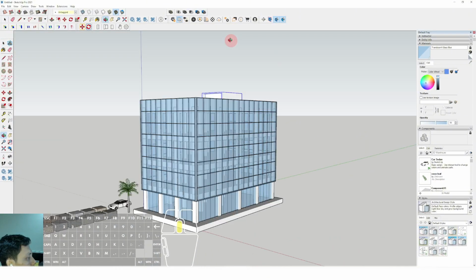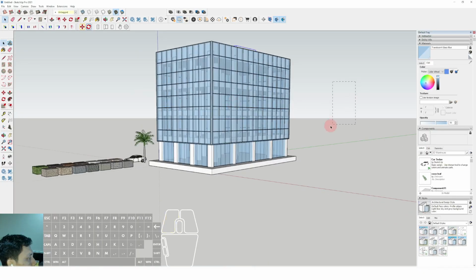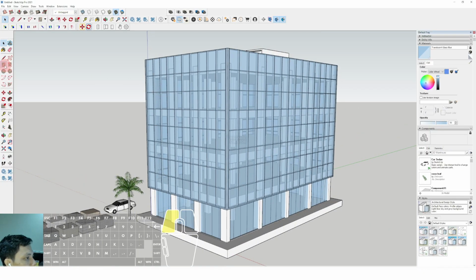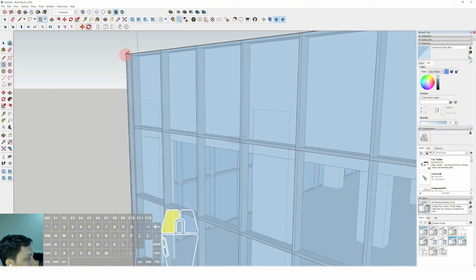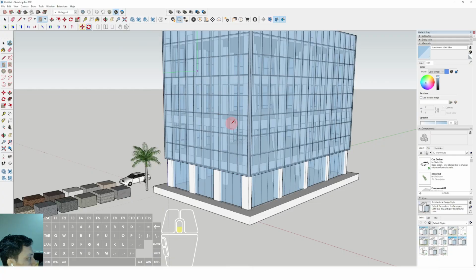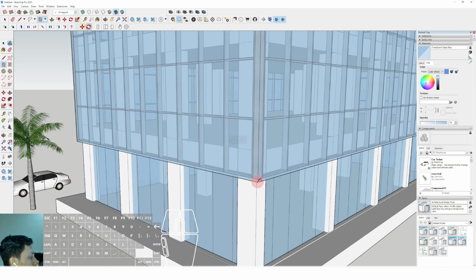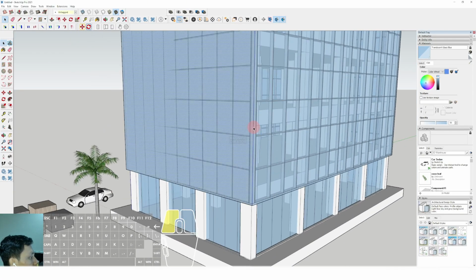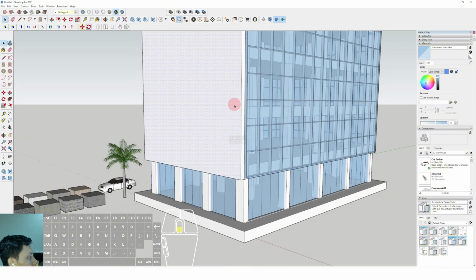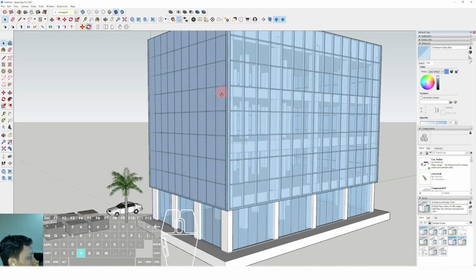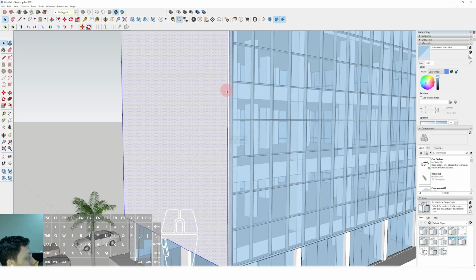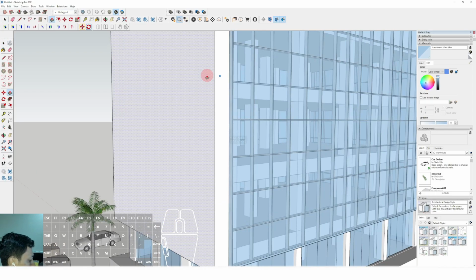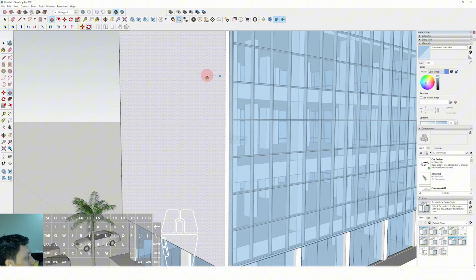This is for the maintenance area on the rooftop, and then now we can select the rectangle, and we can explore this facade, this exterior like this, and we can give a thickness a little bit. Okay, we can give a thickness of 100 millimeter in here, or maybe more. We can add 200 millimeter more.